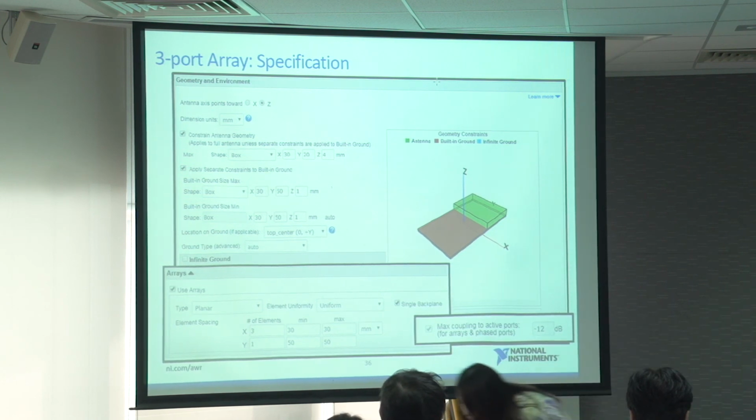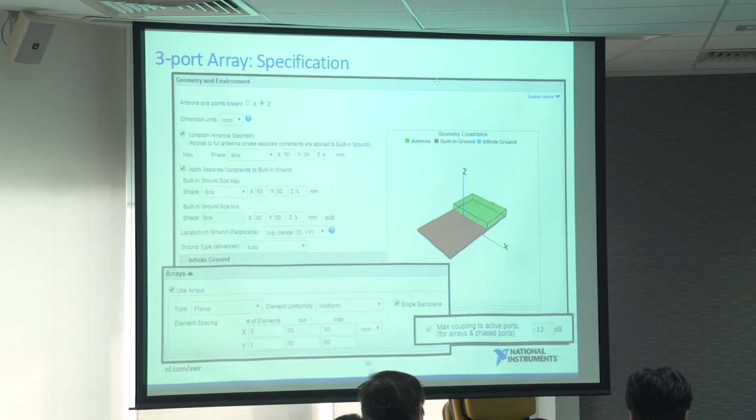So we have this new geometry. This is just one of the antennas, and I replicate it twice. So now I've got an array of 3 antennas, each of which is somewhat smaller. And I still want them to be coupled, say minus 12 dB, and I'm going to make it a 3-element array along one edge of this business card. So next page.